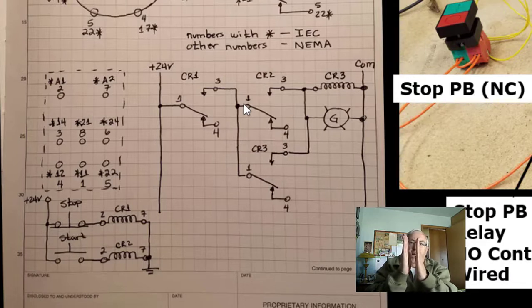It really kind of does this wiping action. And I'm exaggerating that. So when it closes, it actually does this movement this way, which is a wiping, and they call it a self-cleaning contact. So that's why sometimes you'll hear people, including myself, call the pole the wiper, because it's wiping, it's self-cleaning.